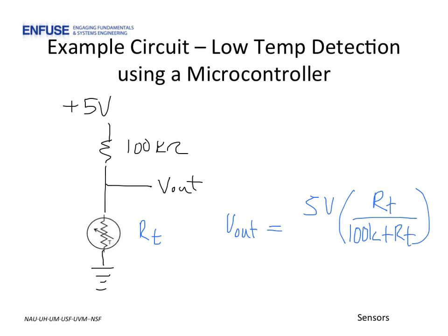The output of this voltage divider can be provided to an analog to digital converter that will produce a number based on the node voltage. In the microcontroller code, you would compare this value to a number that corresponds to your temperature threshold and set an output alarm or heater accordingly.